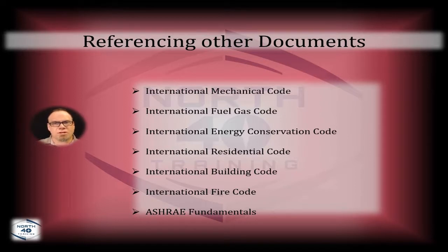What they're going to do is tell you that anytime you're installing fuel gas line, say in a normal residential dwelling unit where you're going to install natural gas piping, anything that you install is going to be done according to the fuel gas code. That's one of the references that you've got in the mechanical code in Chapter 3. So it references everything over to the fuel gas code, but there's an exception. One of the unique things in the mechanical code, other than the references, are the exceptions. The exceptions are also enforceable.